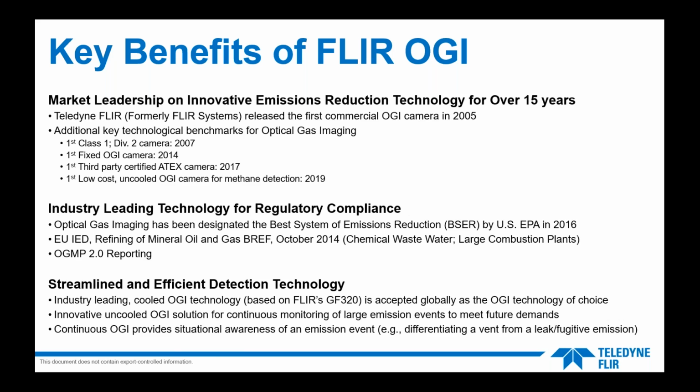Because the technology has been around for many years now, and it's a very powerful tool, regulatory compliance has certainly looked into this. OGI was designated the best system of emissions reduction by the US EPA in 2016. In Europe before that, in October 2014, under the Industrial Emissions Directive, the refining of mineral oil and gas BREF, the best available techniques reference document, listed optical gas imaging as one of three must-use technologies for leak detection.